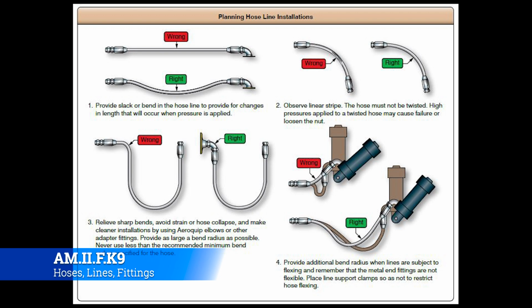The one on the top, there is no breathing room. It's banjoed. It's super tight. So whenever that pressure is applied, there's nowhere for that pressure to go, and so the line is going to eventually bust. Now, it may not do it the first time, it may not do it the hundredth time, but over time, you're going to over-fatigue that line, and it'll eventually explode.